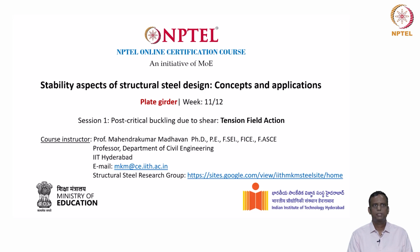Welcome to the course Stability Aspects of Structural Steel Design, Concepts and Applications. In this class, we will talk about plate girders. In particular, we will talk about post-critical buckling due to shear, which leads to what is known as tension field action.